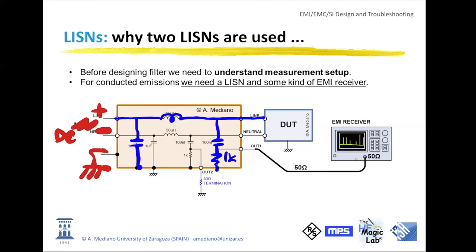In my setup for CISPR 25, instead of 50 microhenries, we have 5 microhenries here, because the inductance in the automotive lines is lower than the inductance that is expected in the mains application. And you can see that we have another LISN. They can be in the same box or they can be in separated boxes with an exact and equal circuit.